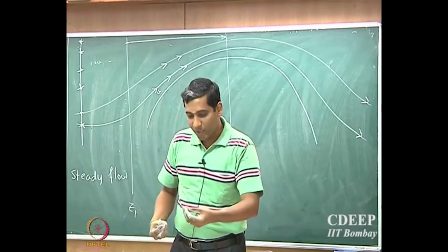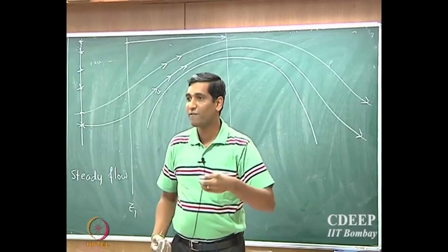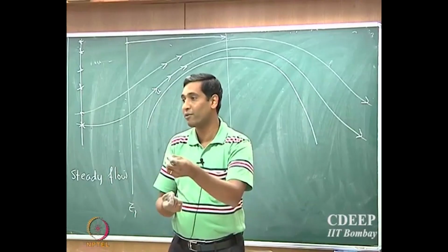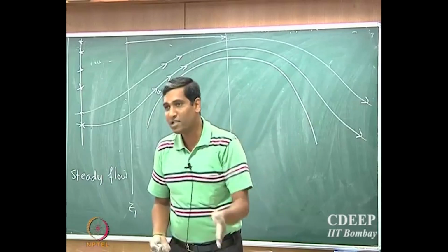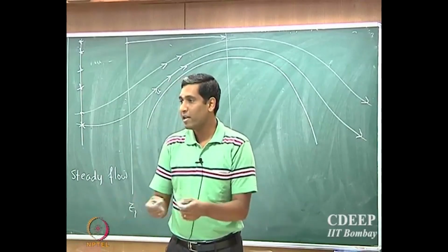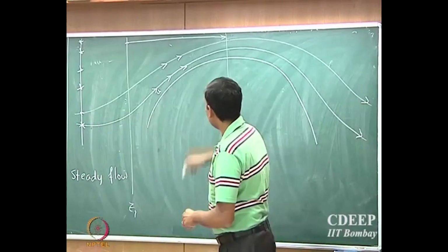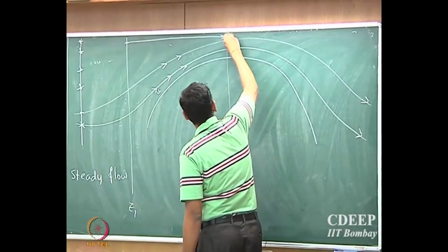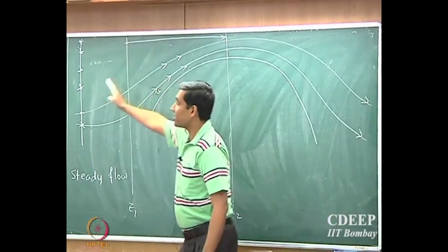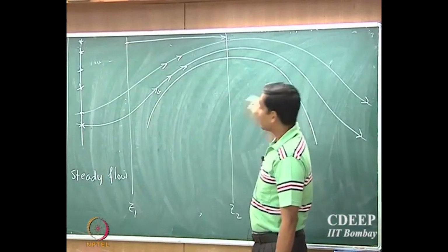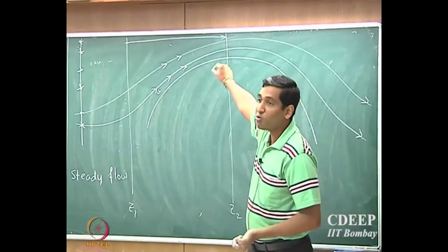In a flat plate, the momentum which is present before the flat plate is experienced is distributed because the fluid particles are now moving in both x and y directions. Before the plate is experienced, the fluid is moving only in the x direction, but in the boundary layer, because of the presence of the flat plate, it is moving in both directions, but the effective mass flow is the same. Unlike in the cylinder, if you want the same mass flow rate, or the same fluid particles which started at some location to cross the location at the same point, then the fluid particles traveling a larger distance have to accelerate in order to catch up.